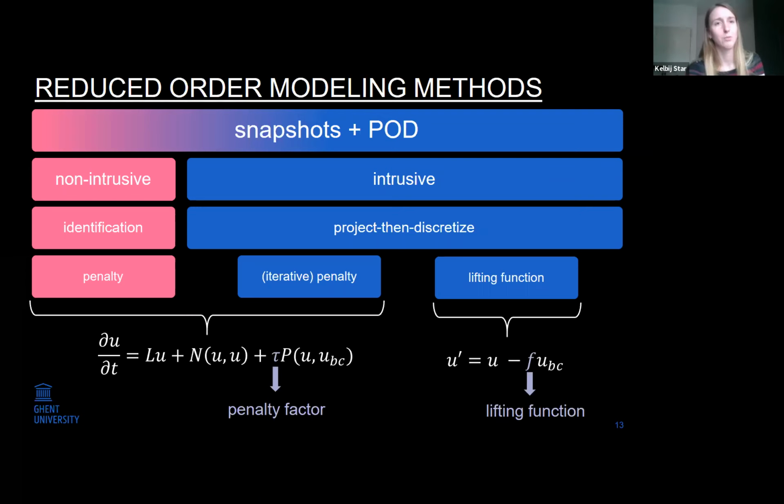But with turbulence, usually at full order level you also have to solve turbulent transport equations and basically some closure modeling. That's always the case, also with turbulence at full order level. And that's something you also then need to do at reduced order level. What we usually try to avoid is projecting turbulence transport equations onto reduced basis spaces, because you have more variables, that's why you have the additional equations, but also the reduced order model becomes complicated and it's hard to get closure.